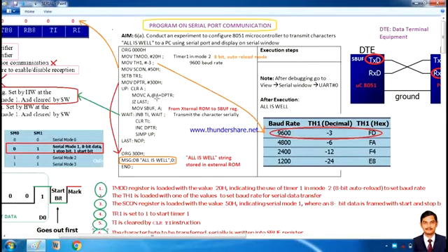The accumulator is 0, DPTR is 300, and at 300 the character A will be accessed and moved to the accumulator. Now the accumulator has the equivalent ASCII code, or equivalent 8-bit data.